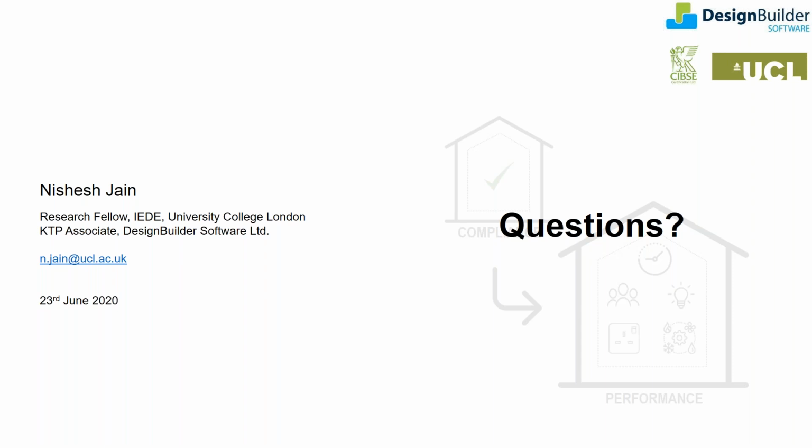But there might be fluctuations, as we have discussed. So sensitivity and uncertainty analysis will be very useful at design stage to quantify that, if you have a particular range within which an input is varying. For example, operating hours came up in this presentation. If you know that occupancy patterns might shift and change, you can analyze how impactful that is compared to, say, the uncertainty in construction quality in the building. So comparing construction quality versus operation, which is more important? Obviously construction quality will affect, but maybe the other thing affects more, and then you try to identify measures to minimize those risks.